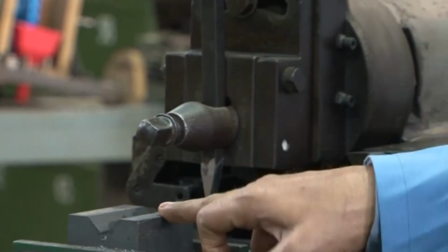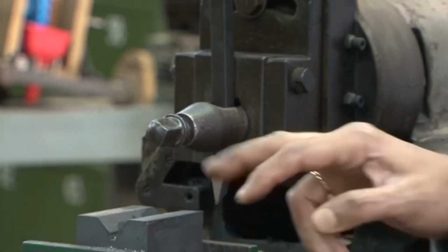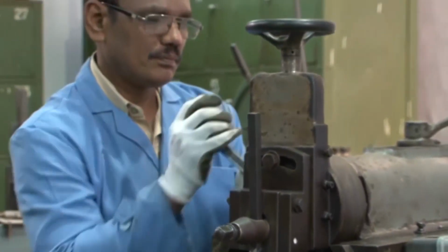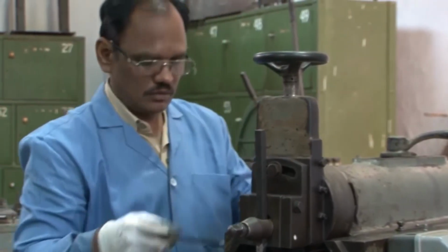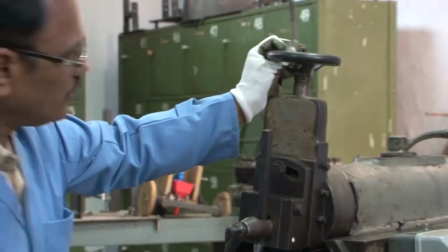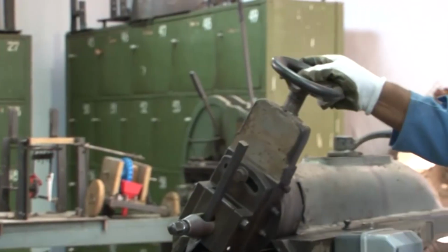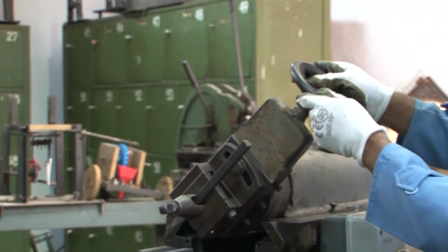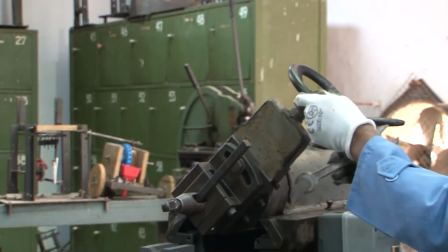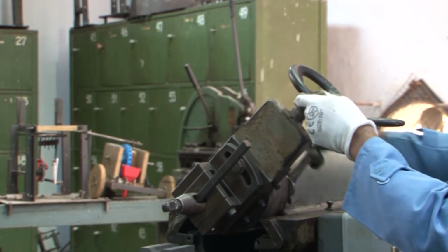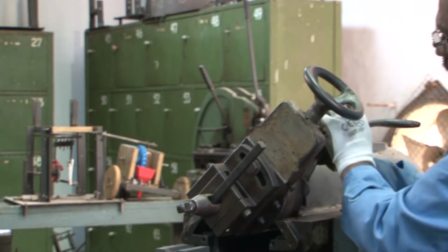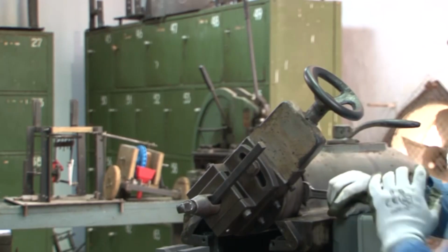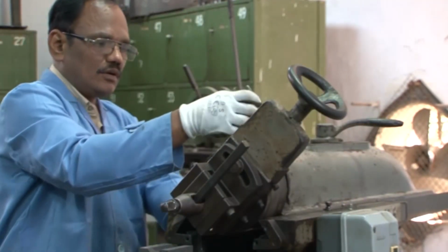So, that will be demonstrated to you right now, and after that how this grooving can be done, that will be shown to you. Tool head has to be moved and tool head has to be inclined at an angle of 45 degree, as I said. So, you can see that the arrangement is being made for the inclination of the tool, and the tool is being inclined, as you can see here, and there is a graduation, there is a scale according to which you can find out what is the angle of inclination, and the angle of inclination will be 45 degree, and then you tighten this and the tool is fixed at that angle, which is 45 degree. So, then the right hand side inclination of the dovetail will be completed by this. Afterwards, we will go for the left hand side inclination, and the entire dovetail groove can be made that way.